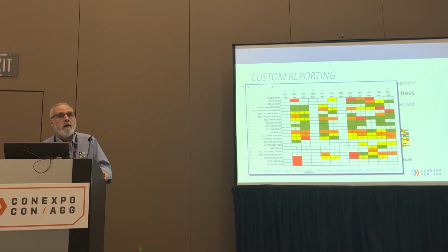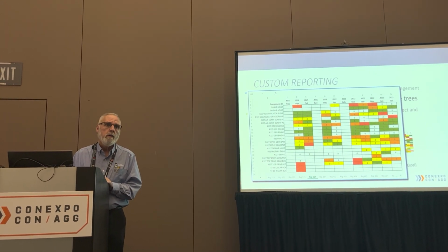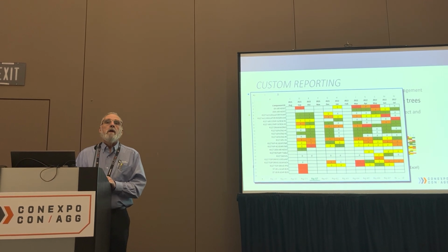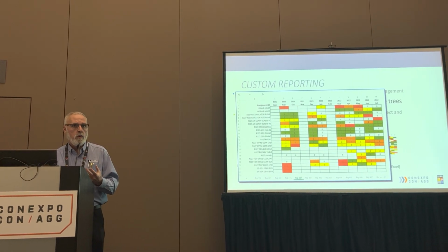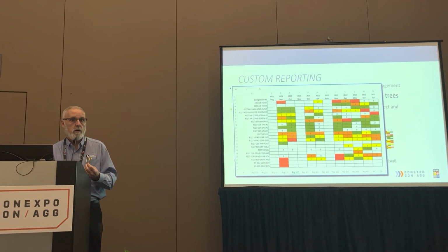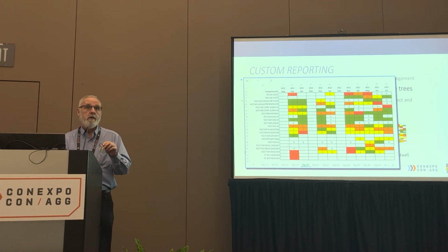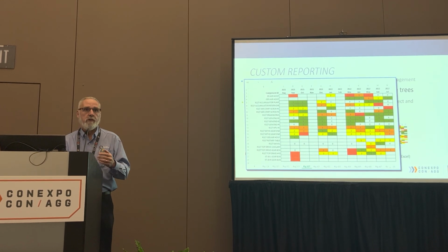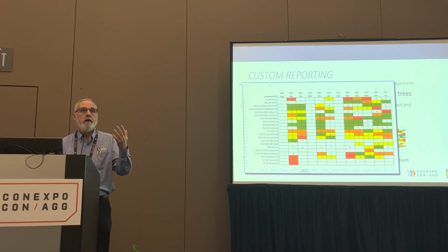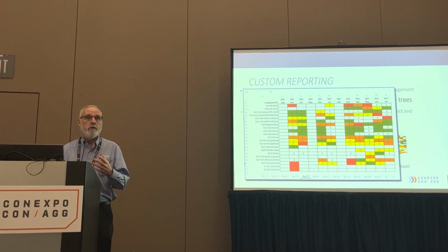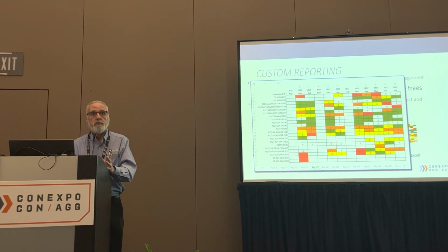Do you find that in your experience your customers are making these decisions purely based on the color that you're putting on the top of the report? Some do. Some of those, as I mentioned earlier, that are auto-generating work orders are doing it on severity. Others have really tailored that down to specific analytes. In that example, if iron reaches this parts per million, then we know for us in our industry, that's a problem, because we've had failures when it's reached that high historically. Does that answer the question okay?